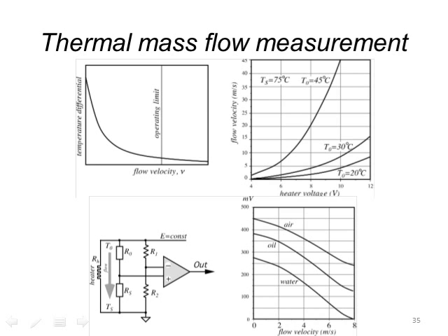You can look a little bit over the flow velocity characteristics at different temperatures. You can see it can be quite nonlinear, it can be a little complicated. Calibration is absolutely required with these types of sensors. They can be quite useful because of their low cost, but you have to use them over a limited range, and they have to be well calibrated for the particular gas that you want to detect.